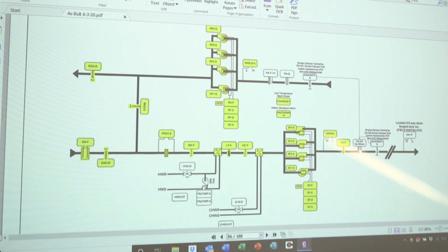There is heat trace on all this, with the heat trace controller mounted in that box, so be mindful of that. The freeze pump runs continuously whenever the temperature falls below a predetermined adjustable set point. The heating coil will modulate to maintain discharge air temperature in the heating season.